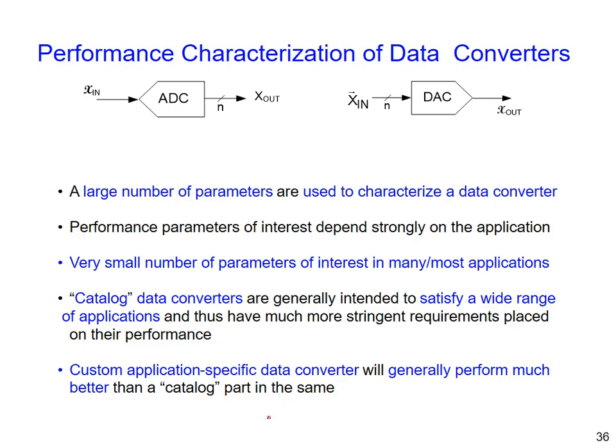Right now, we are only concerned about the so-called linearity, but we still have a lot of parameters to check whether or not your data converter is good enough. Okay? For the commercial data converters, they list, I guess, around 20 parameters. That's too much. To be honest, for our application-specific data converter, usually we focus on very few parameters. I guess, first of all, INL. Secondly, ENOB.